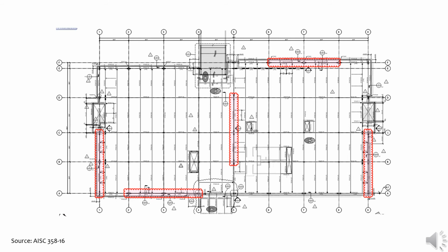With the SidePlate technology, stiffer moment frames can be modeled. This typically reduces the number of moment connections by 20 to 30% compared to conventional moment frame buildings. You will see in this framing plan that only a pair of 2-bay SMFs is required along the x-axis and 3 2-bay SMFs are required along the y. Additionally, the increased stiffness allows the design team to minimize the beam and column weight by 15 to 25% of the lateral steel tonnage.